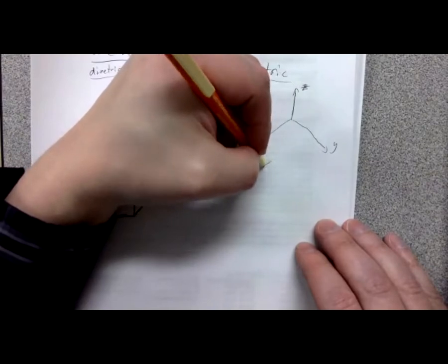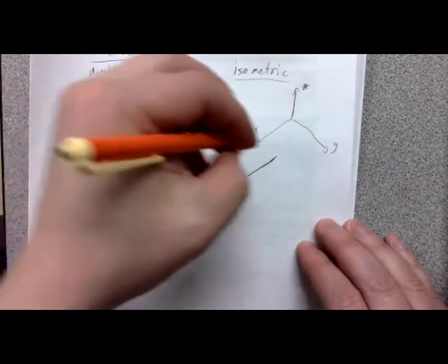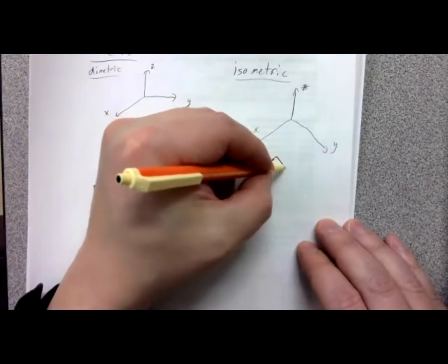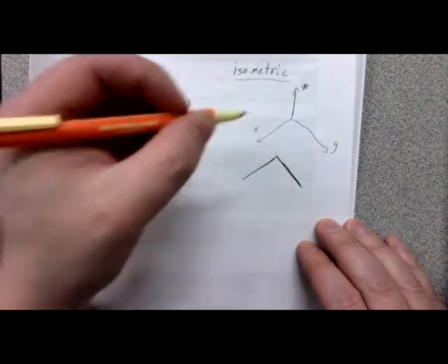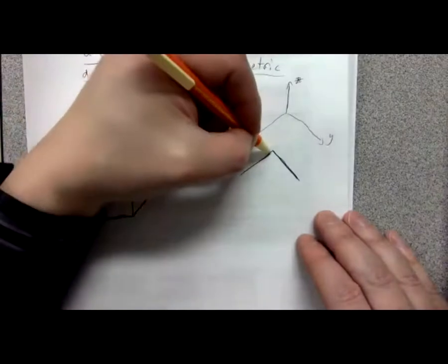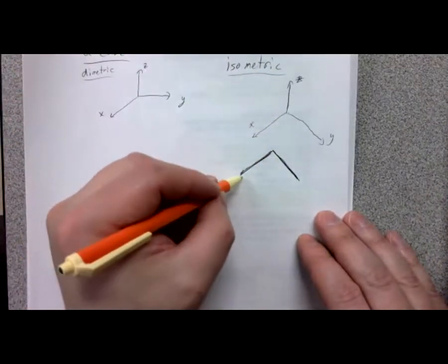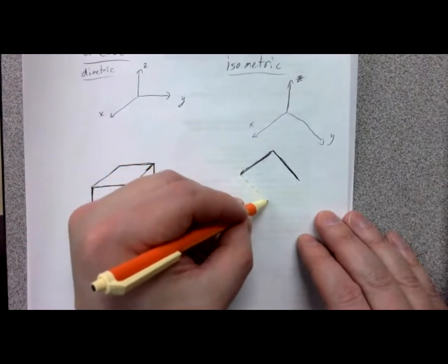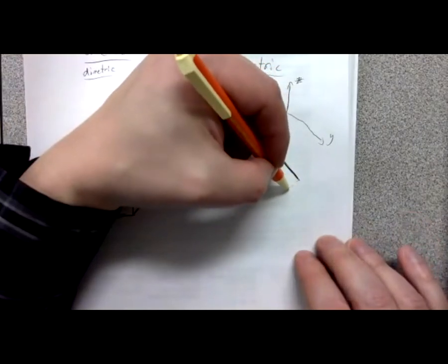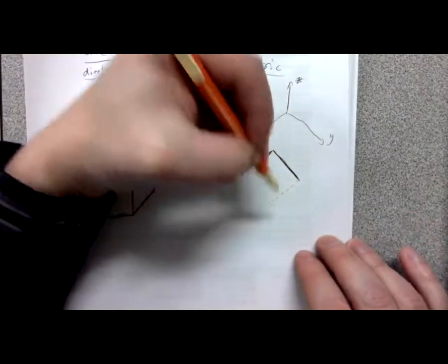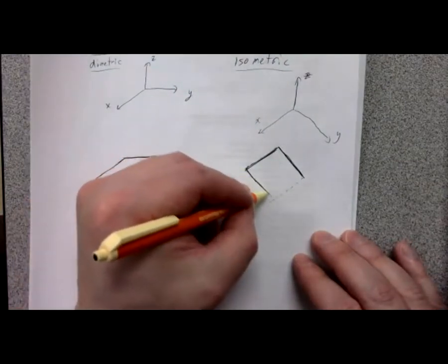So I'm going to draw the top face first. Top's this way and this way, so I'm going to draw on the top face of this cube lines that are roughly parallel to my x and my y. And then from those corners, I'm going to dot those lines out. I don't know where this point here is, so I'm going to find it by where those two lines would intersect. And that tells me, all right, we'll go back and dot and darken those in.